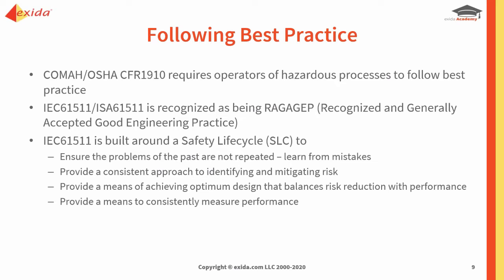So again, if we don't follow the requirements during operation and maintenance for proper testing, proper maintenance, replacement of devices or refurbishment of devices as they get to the end of useful life, then we're very quickly going to have a SIS and SIFs that will deteriorate and will not be providing the level of protection that we need.